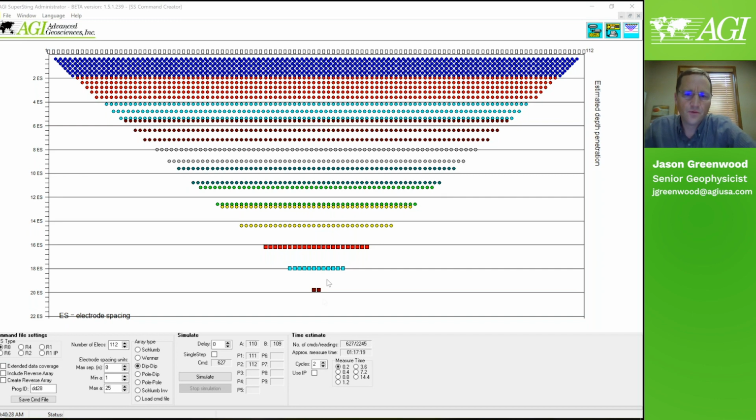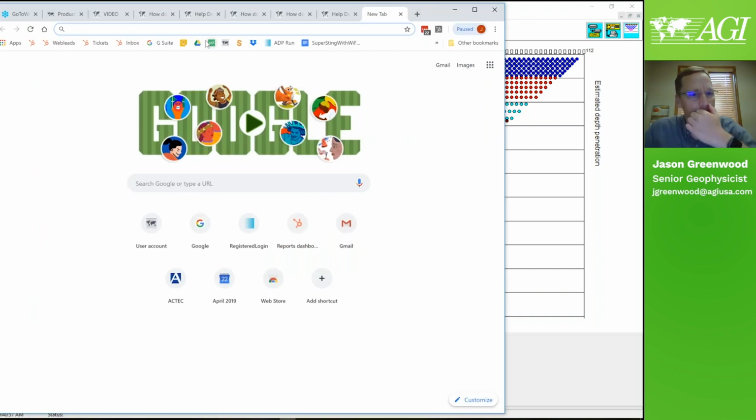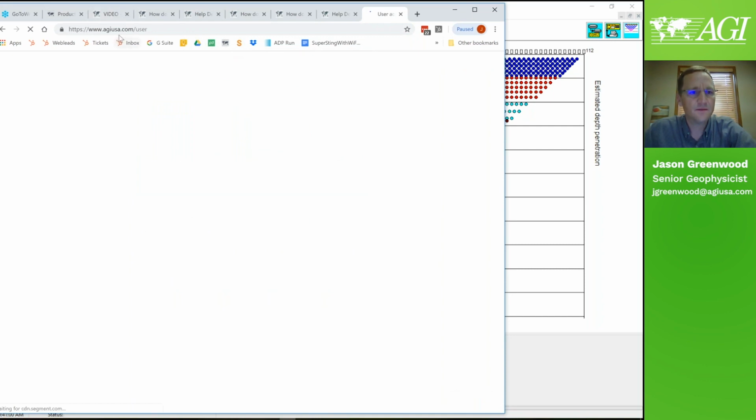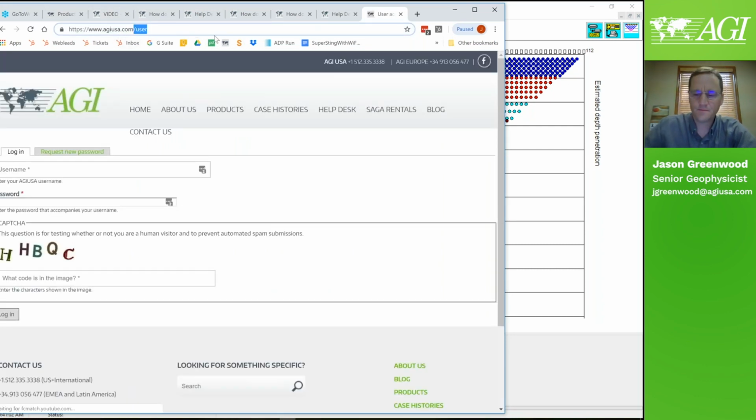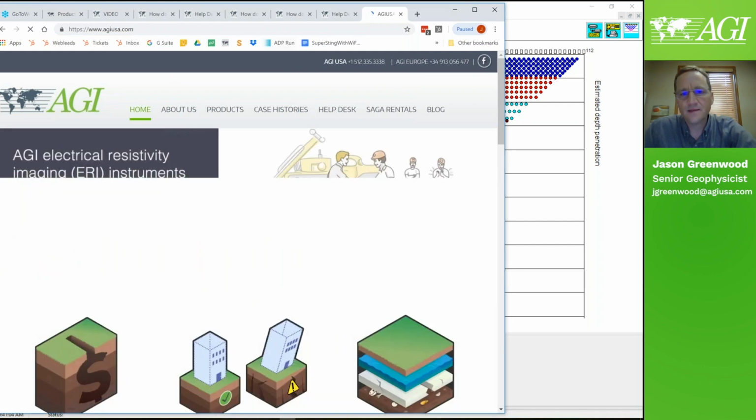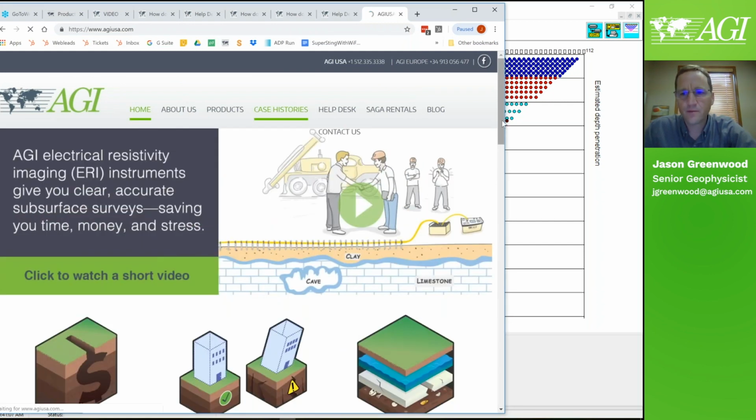So it's 1 hour and 17 minutes with resistivity alone. It would be 1 hour and 54 minutes of just machine time to measure IP. And I know that there are clay layers of interest in the near surface, but that may have higher chargeability, but that's not the dominant target. The target they want is the salt water. And that case history is here on our website, under the case histories tab at the top.